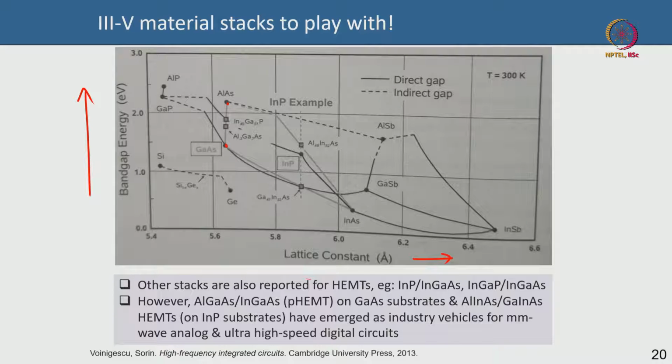Now, if you recall, we talked about 50, and this is indium arsenide by the way. So, this line is your indium arsenide. As you keep changing the indium content from 0 to 100%, you move along this line in terms of lattice constant and band gap on both y and x axis. So, when I say 15 to 20% of indium content in InGaAs, you are probably somewhere here. So, around 10-15% InGaAs, and this will be 100% InAs, of course. InGaAs and GaAs are lattice mismatched by probably around 2%, for instance with InGaAs 15%, but that is where you actually are.